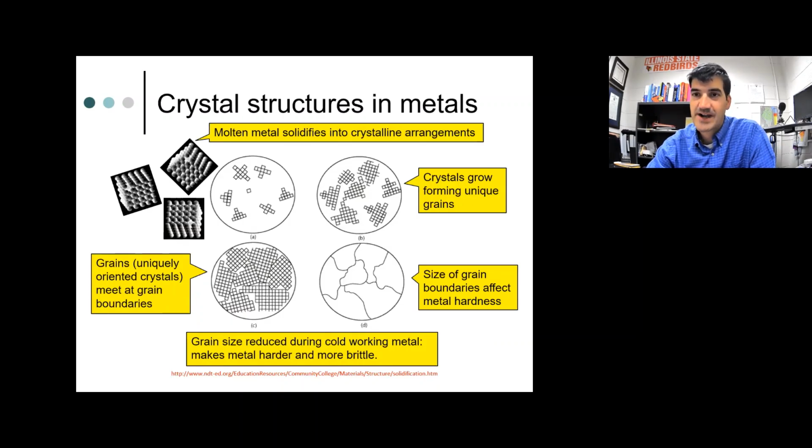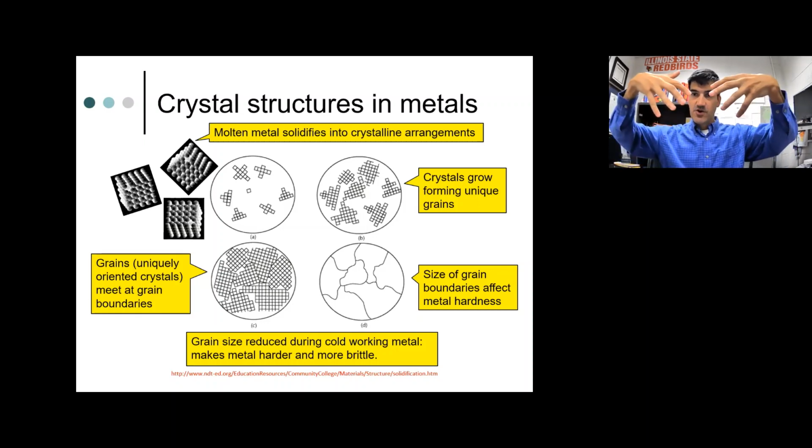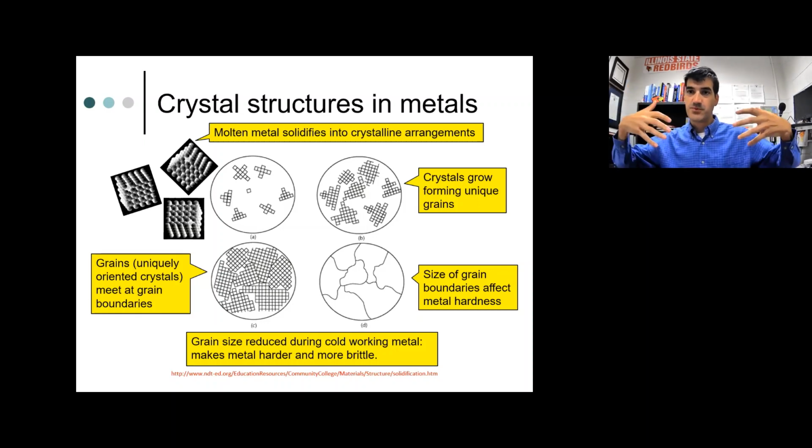And we also talked about grain structures last time and how it's important to know that any material, whether it's water or molten steel or any liquid that is freezing, doesn't just instantly turn to solid at the freezing temperature. It takes a finite amount of time to freeze, and when it freezes, it starts out by creating solid structures at the inception points, and then gradually the solid grows out from those until they all meet together at these grain boundaries.